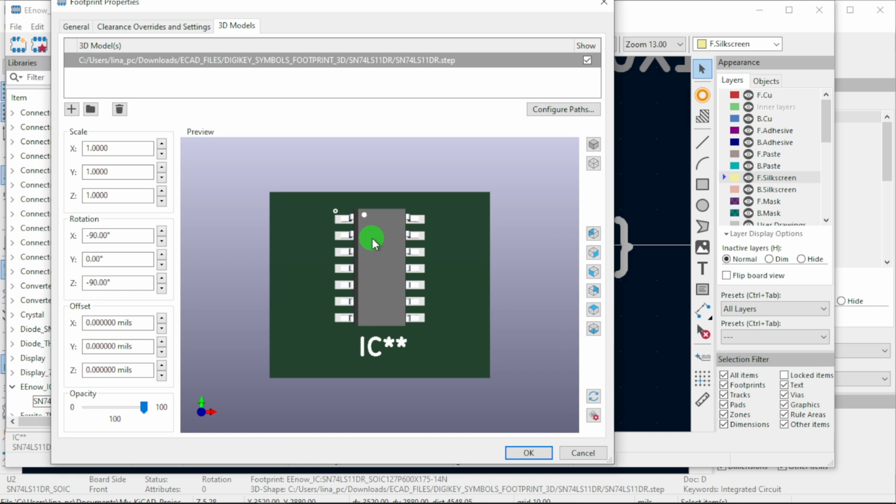My layers: board finish, silk screen, board finish. These are the 2 layers here. If you want to add more layers, you can click here. 4, you can go up to 32. Board finish. These numbers I also have from different manufacturers, who have different numbers here. You gotta put them in if you can find them.